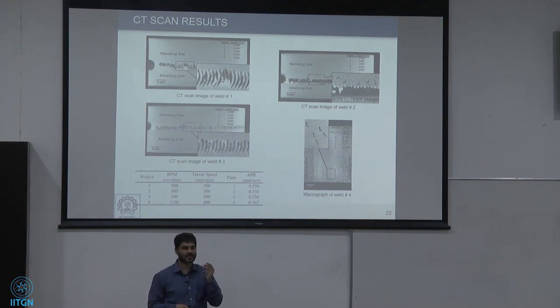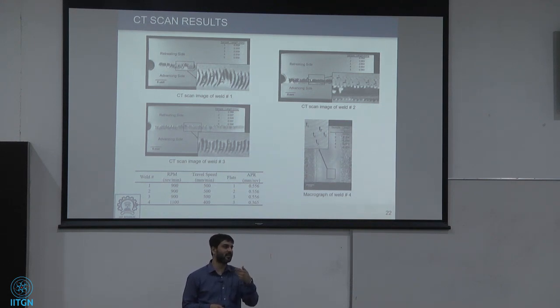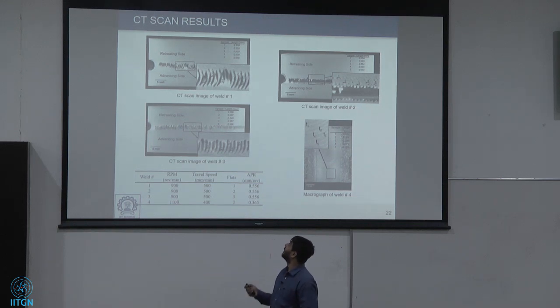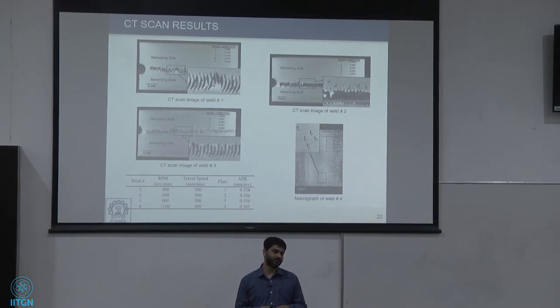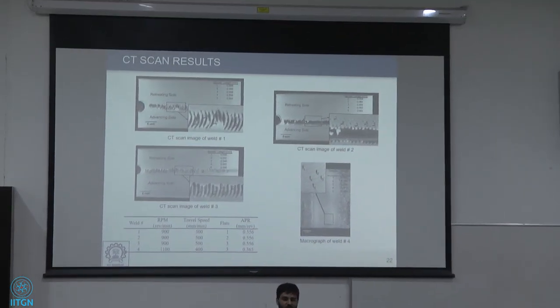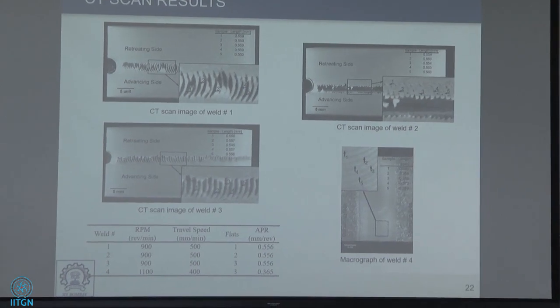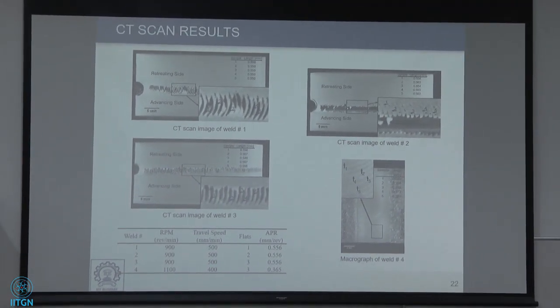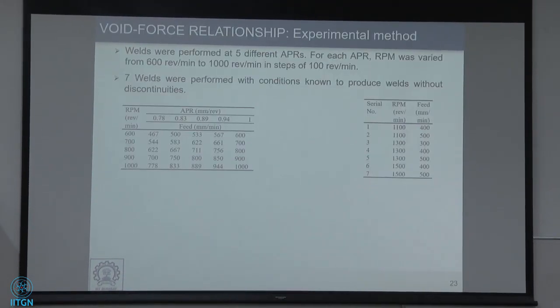This is because at this end material is sticking with the tool pin itself as it is being moved by the tool pin. Then at different locations I measured the distances between these successive arcs, and it could be seen that the numbers are very close to the advance per revolution, which is the ratio of the travel speed to the tool revolution frequency, RPM.